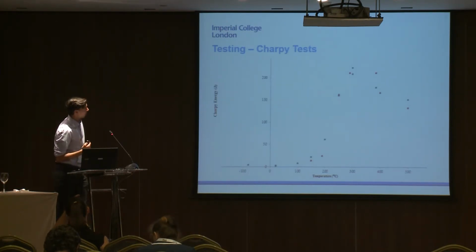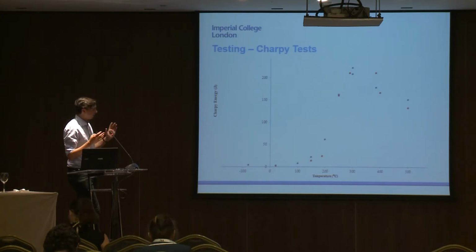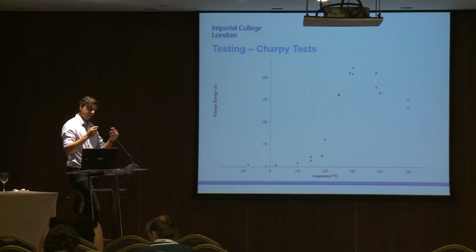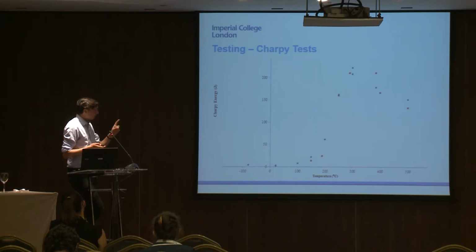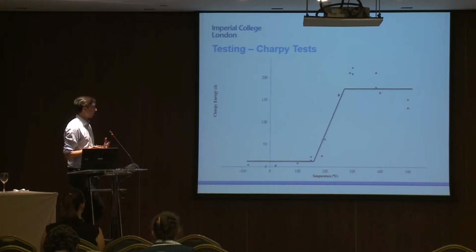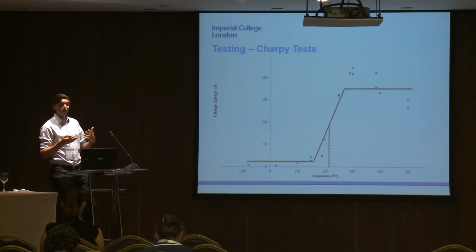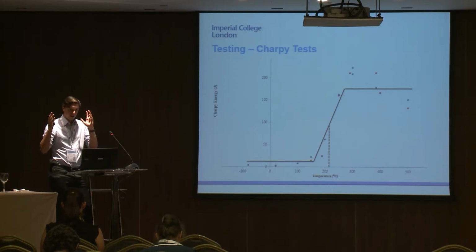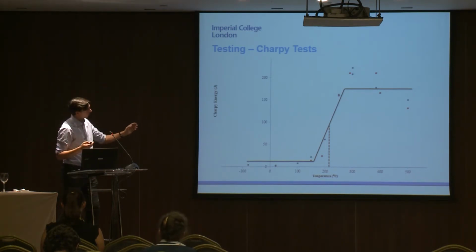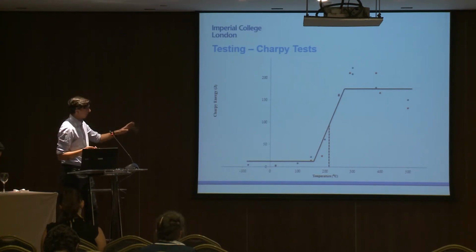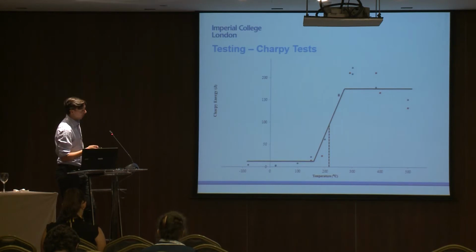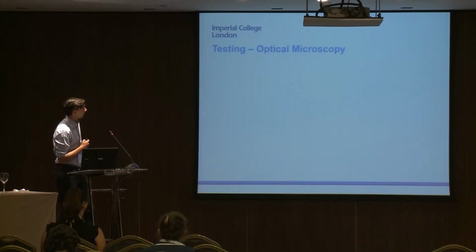So, first of all, our Charpy results. We noted that through the thickness of the slab, we're getting the same ductile to brittle transition temperature, regardless of the location through the slab. You're getting a very high ductile to brittle transition temperature, somewhere around 220 degrees. This is great news, because it means that what these steel plants are doing by keeping them really hot and not letting them cool down is making sure they stay very ductile. If they let them cool down, you're entering a very brittle range when the slabs get below 150 degrees Celsius.